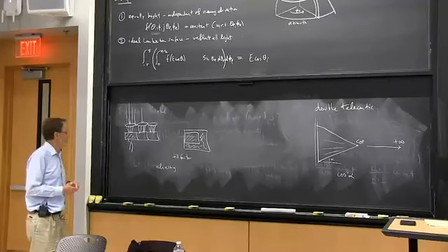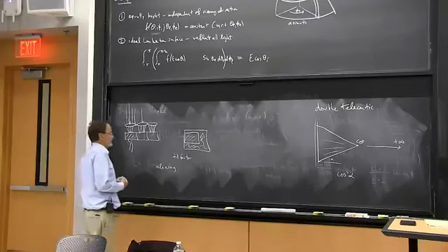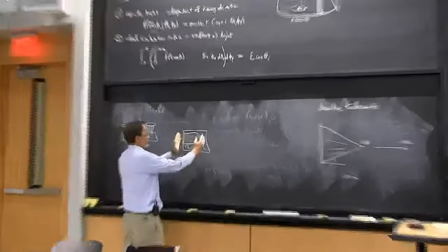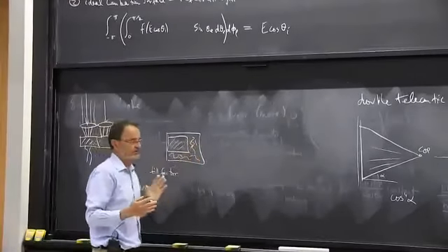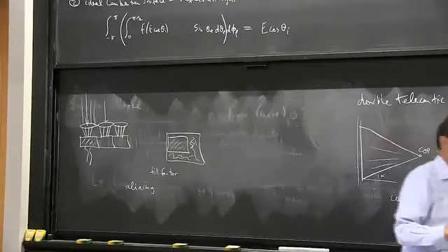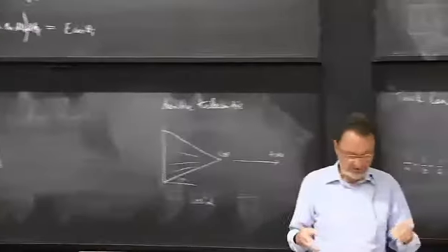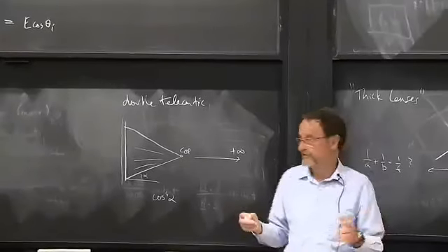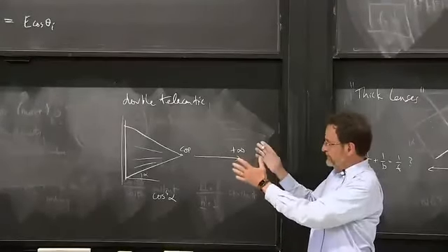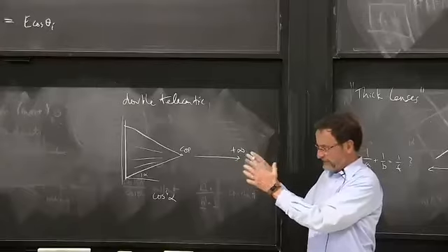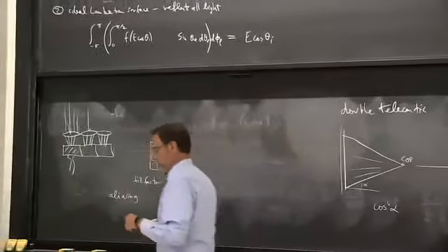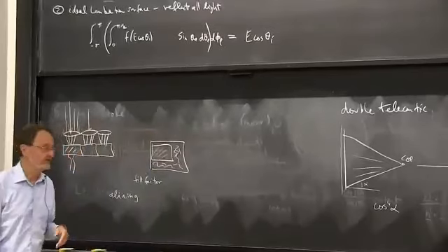And what's the relevance here? Well, if we're measuring over the whole area, we're performing a crude form of low-pass filtering with block averaging. The real low-pass filter is a sinc function, but we can't build that. So if we have the large pixel, we get a certain amount of advantageous low-pass filtering, and fancy cameras have additional mechanisms for this.